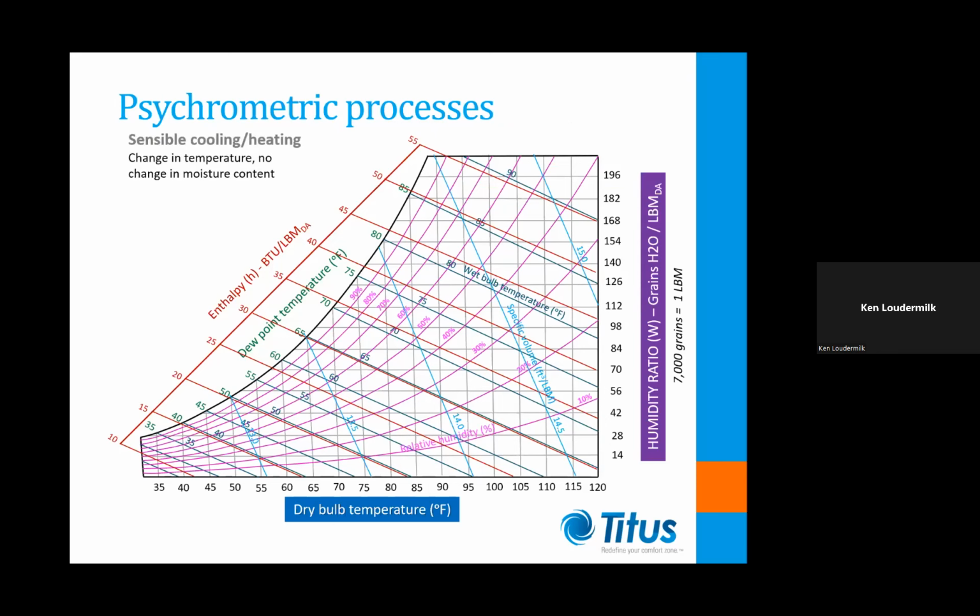The most basic HVAC processes are sensible heating or cooling. These processes add or remove heat from the air without affecting the mixture's absolute moisture content. For example, a sensible cooling process occurs when an air mixture's dry bulb temperature is reduced without reaching the saturation line, thus maintaining its moisture content constant. Note that a sensible cooling process lowers the mixture's wet bulb temperature, specific volume, and enthalpy, while its relative humidity and density increase.